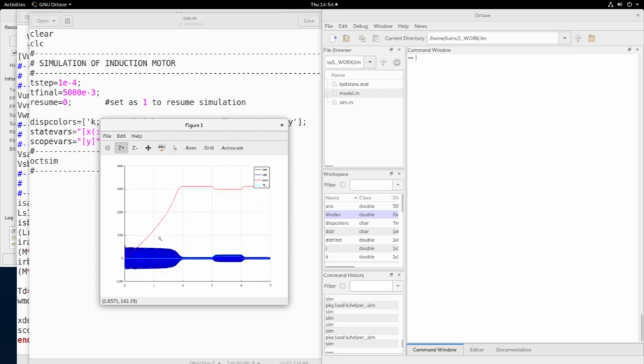So if you look at the speed ramping up, here the load is J d omega by dt. There is a d omega by dt. During this time, the torque is the inertial torque, wherein the machine is being brought to a stable speed, and J d omega by dt has to be overcome. So that is that current.